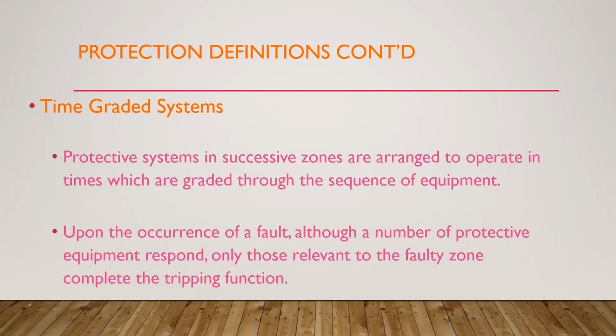And of course, the other generators say, well, since you all tripped, me gone too. I mean, it's not like that, but you get the picture, right? Yes, sir. And so everybody tripped. Why? Because a man was just too lazy to check for the short and ground and to clear it before energizing the line. Right?